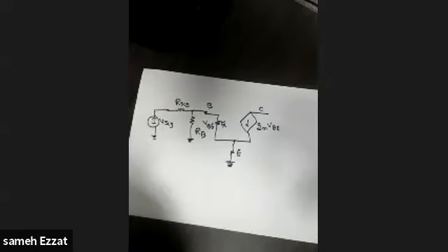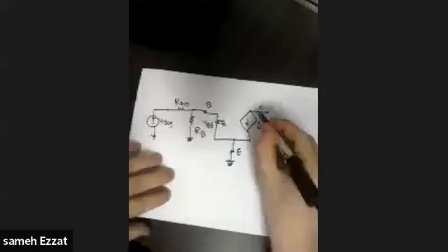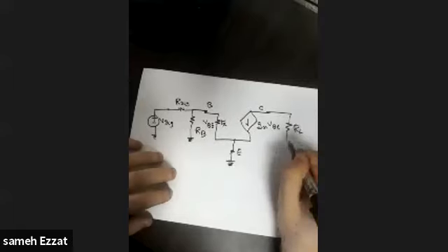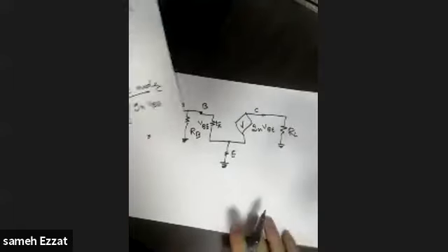What about the collector? Okay, first the collector. Now again, it's a capacitor. So the capacitor is a short circuit. So this is a wire, and then we have an R load to the ground. And also, here we have the collector point connected to RC and then VCC.